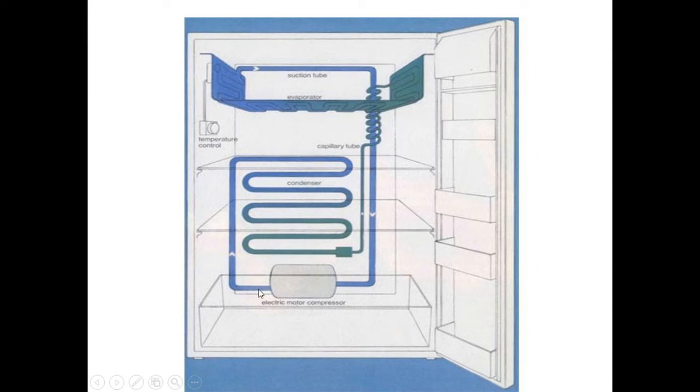And at the bottom you can see a compressor, a sealed compressor. You can see a black colored compressor which is placed inside a shell. So that is called a hermetically sealed compressor. That is actually a reciprocating compressor. Now you have one more device called capillary expansion device. In a smaller capacity system, we have a capillary tube as an expansion device. But in some higher capacity systems, instead of capillary tube, we will be using an expansion valve.